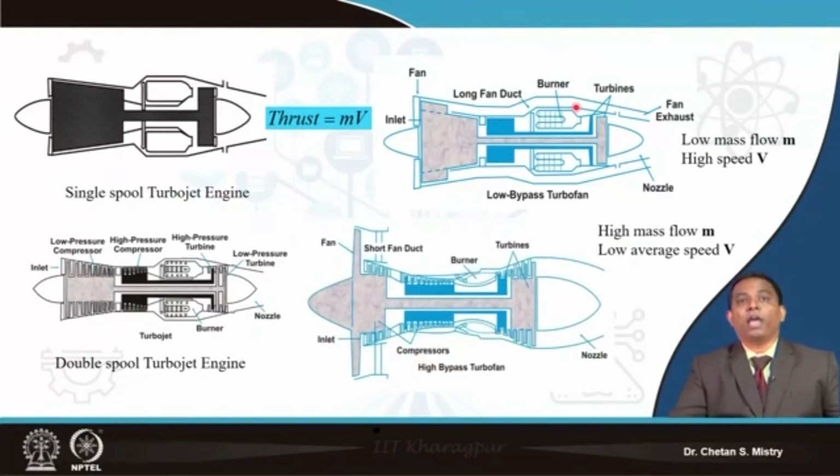Now for aero applications, when we are talking about the big engines, this is a high bypass ratio engine. This is what we have discussed earlier. We have a large size fan, followed by the LP compressor and the HP compressor, rotated by a two spool configuration. Here also, as we discussed, our major concern for aero application, for our commercial airlines, is fuel economy.